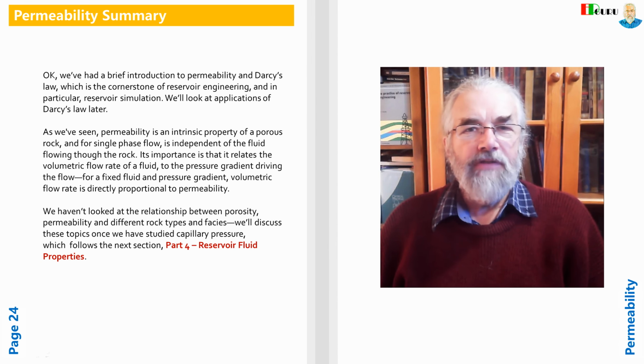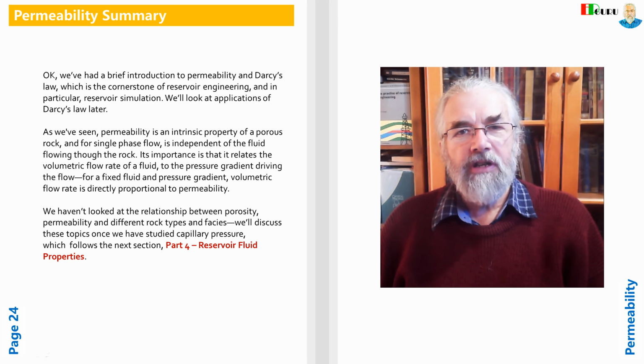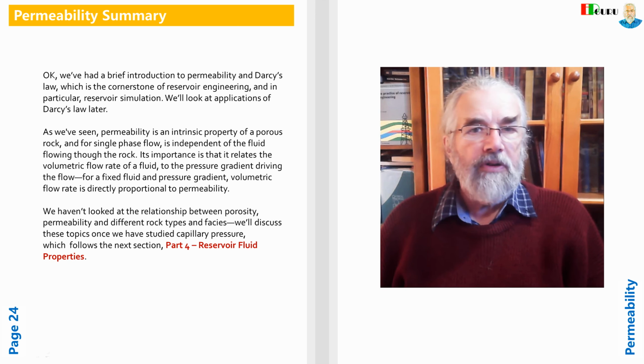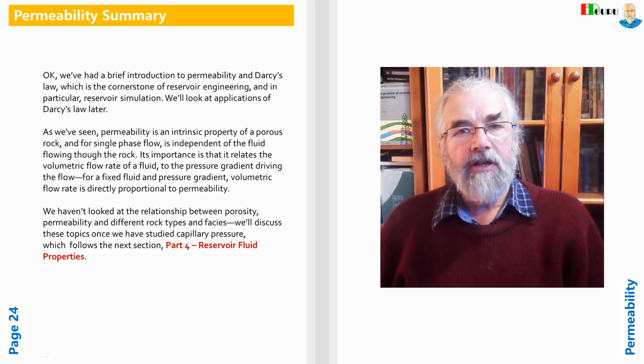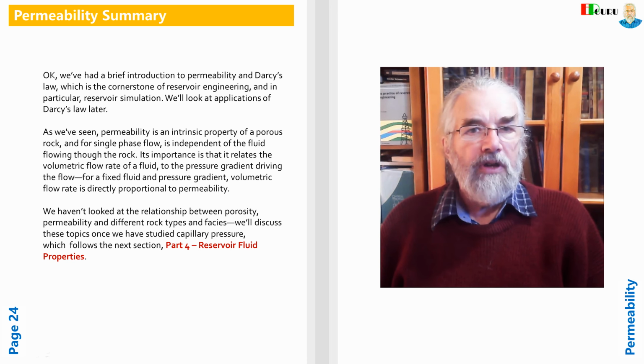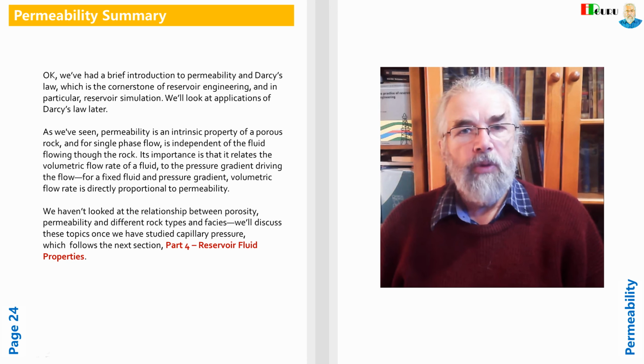Okay, we've had a brief introduction to permeability and Darcy's law, which is the cornerstone of reservoir engineering, and in particular, reservoir simulation. We'll look at applications of Darcy's law later. As we've seen, permeability is an intrinsic property of a porous rock, and for single-phase flow is independent of the fluid flowing through the rock. Its importance is that it relates the volumetric flow rate of a fluid to the pressure gradient driving the flow. For a fixed fluid and pressure gradient, volumetric flow rate is directly proportional to permeability.